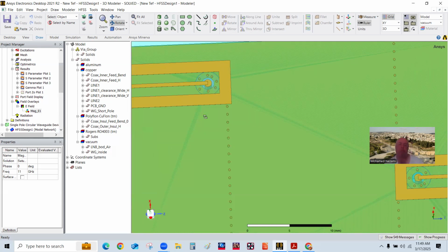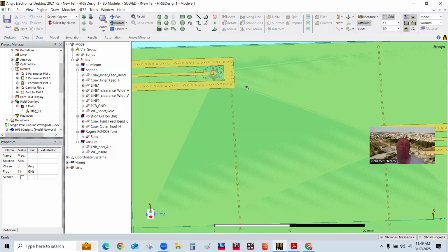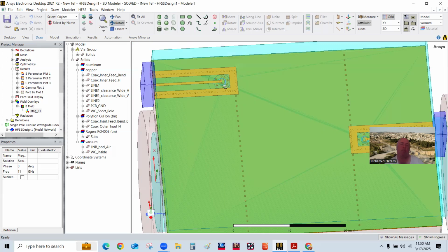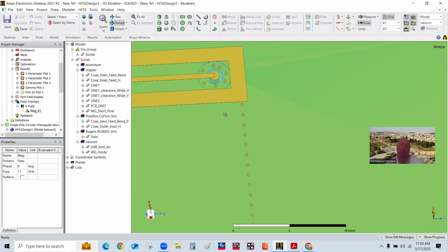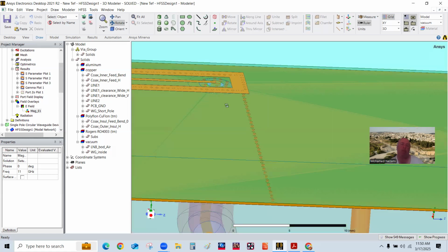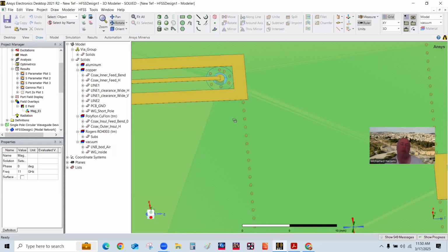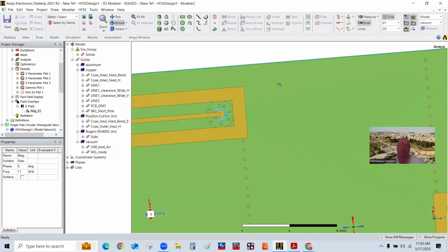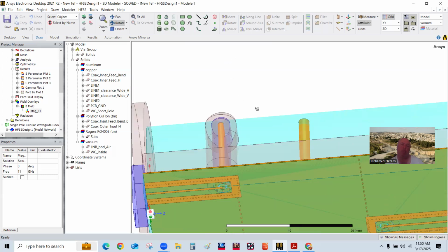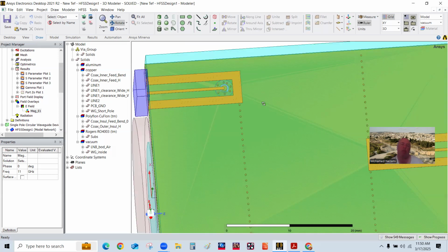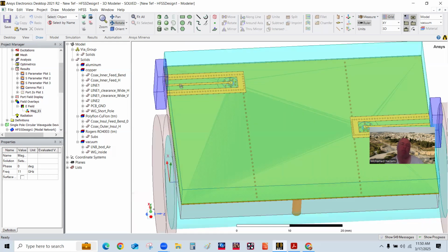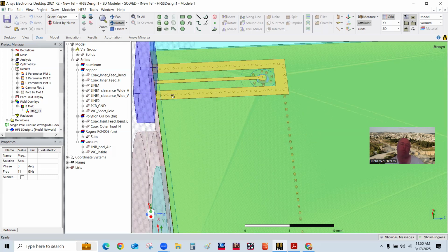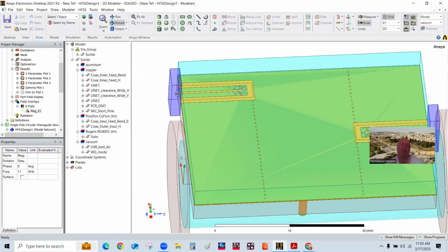a via transition that implements a coax section in the stack layers themselves. I had a circular array of ground vias to implement the outer shield, and the center conductor is this guy here that picks up the signal. Then we go out, and of course I have a microstrip line that goes this way, and we pick up the signal in here for analysis.